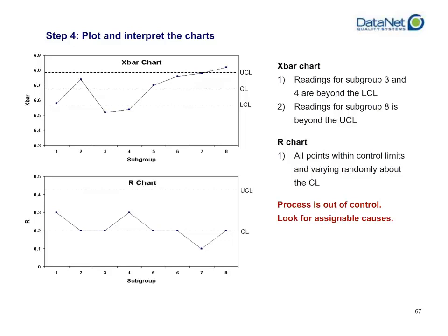You would have or should have tried to investigate what was going on with subgroups 3, 4, and 8 to see why your process was out of control. Further, since this type of control chart was not done in real time, and you wanted to determine whether or not you were in control, the last subgroup that you collected is in fact the state of your process. So in this case, subgroup number 8 is currently out of control. Therefore, the process itself is out of control. You really should go and investigate what the cause for that out of control point is.